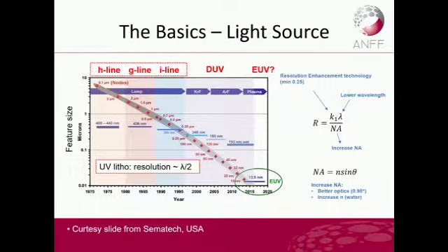So as you can see, if you are scaling using the H to I-line region, you have a resolution approximated to about half of lambda. So in the industry, you will be able to scale down to just under 200 nanometers with your 365 nanometer wavelength. Things changed a lot since the introduction of 248 nanometer onwards. And you can see that, how is this even possible, to make 10 nanometer features these days using 193 nanometer lithography?